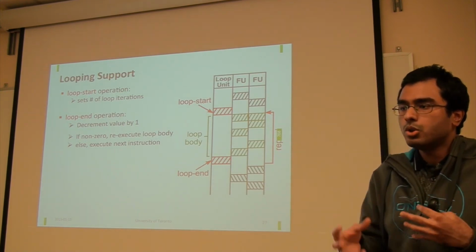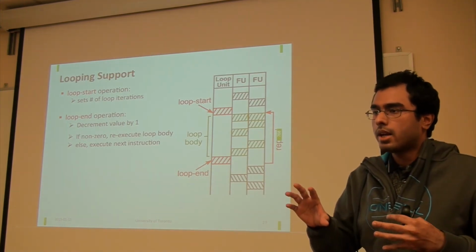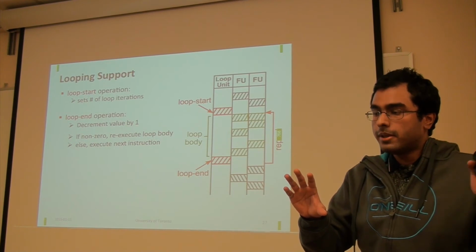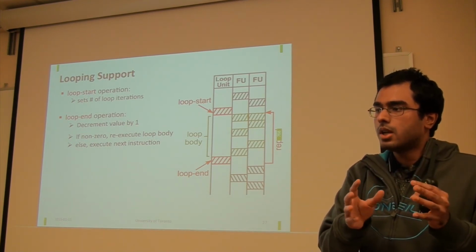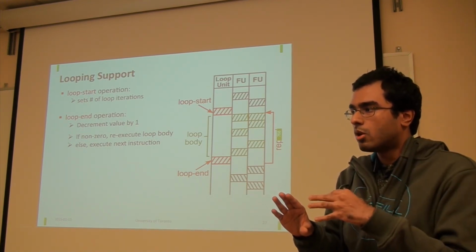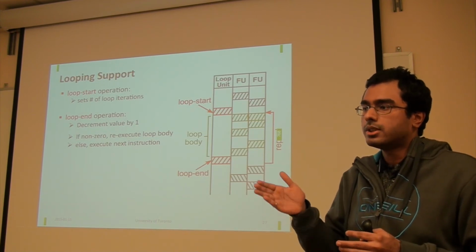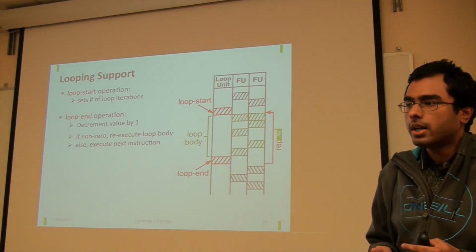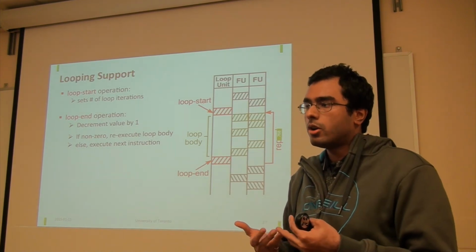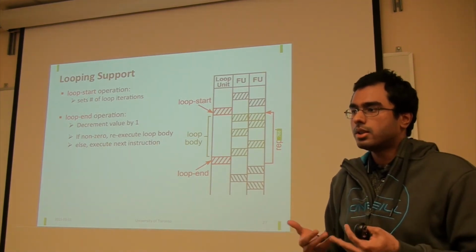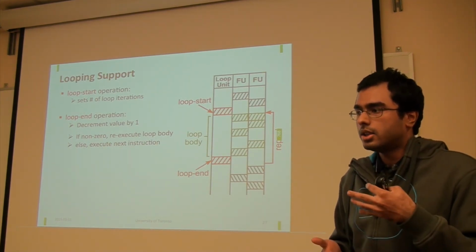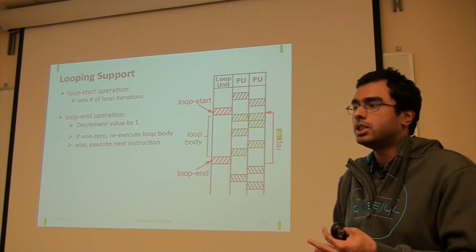You obtain high throughput by prefetching enough data into your FIFOs so that you can stream it into your compute pipeline, and at each cycle you're doing something useful. But if you do not allow your OpenCL compiler to do that, then you're significantly reducing the throughput you can achieve.